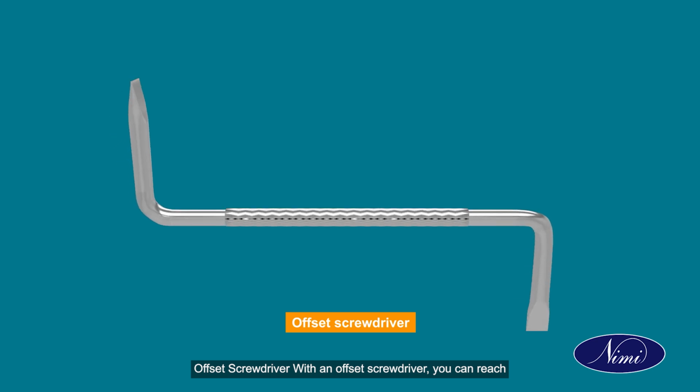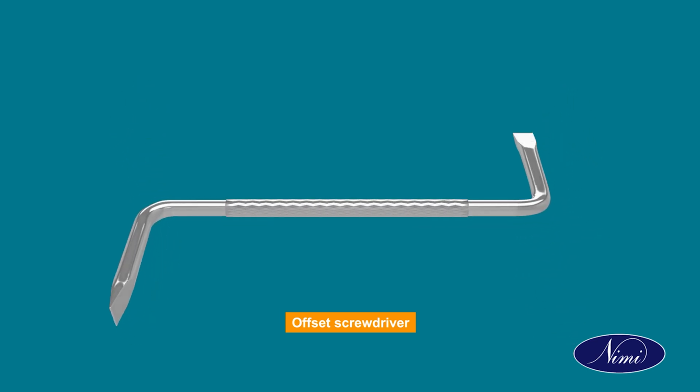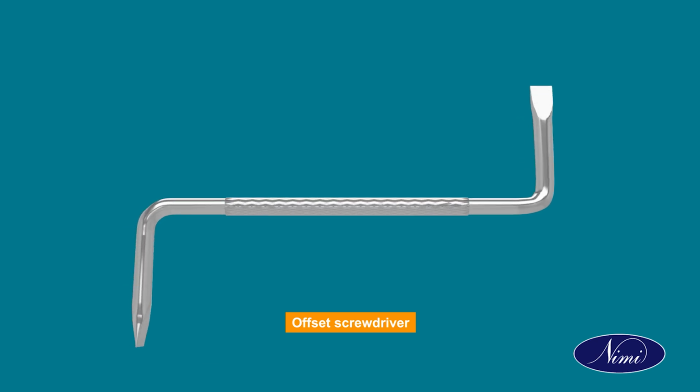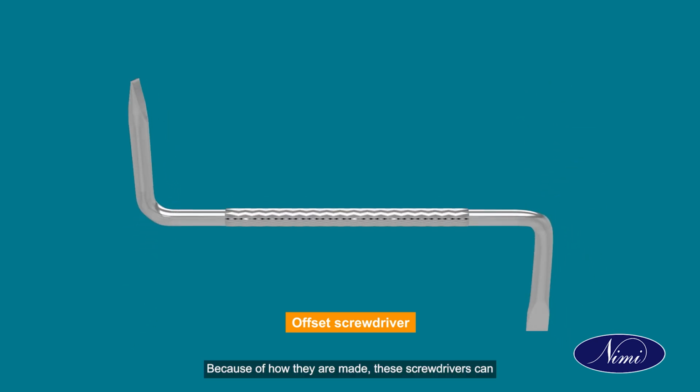Offset screwdriver. With an offset screwdriver, you can reach screws that are in a blind spot. These blades are short and the tips are at a right angle. Because of how they are made, these screwdrivers can turn screws with more force.